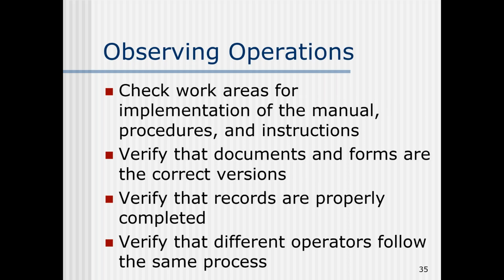And there's a time and place just to be quiet, just to observe, watch, listen to what's going on. Listen to the equipment. Does it sound screaming like there's metal on metal rubbing and maybe lack of effective maintenance? Is there a lot of clutter and dirt and miscellaneous stuff laying around that gets in the way of a good, smooth workflow? Are people hustling back and forth instead of moving in a deliberate fashion? And all those things play into the results of the audit and where we look for further concerns.